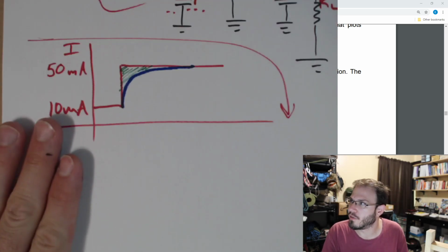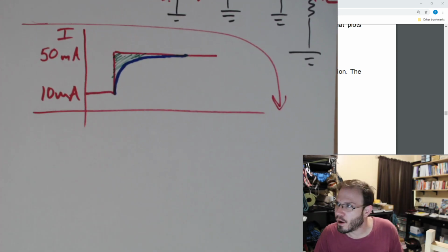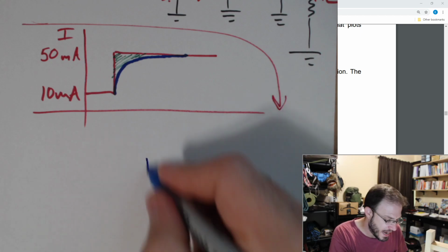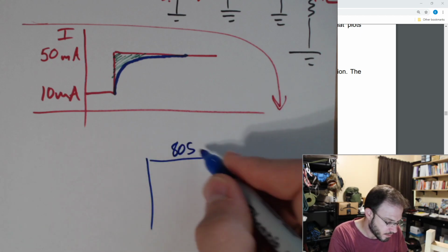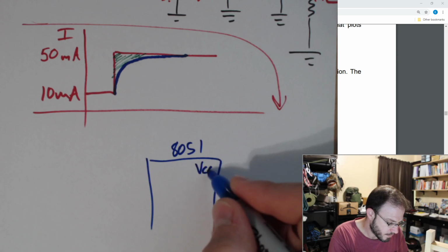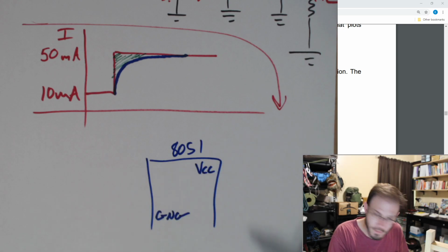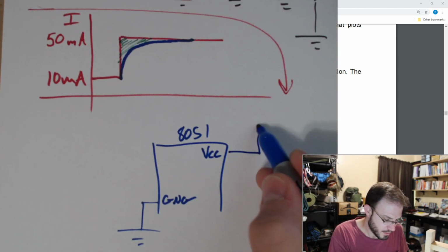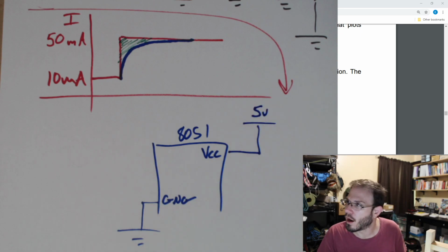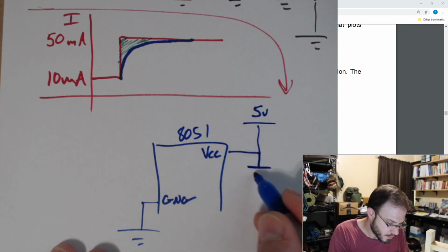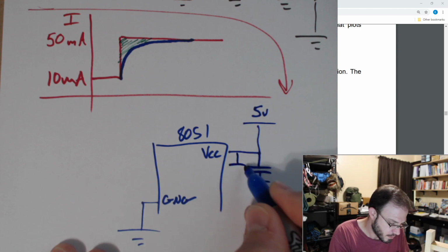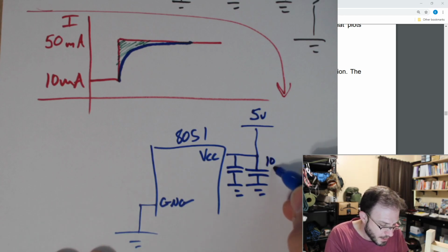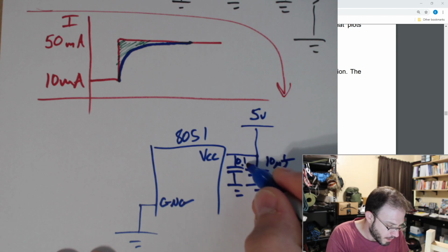And all of your digital devices, if you are in 262 and you're working with that 8051 board and you look at the schematic for that 8051 board, they're always going to attach ground and attach power, but what they're going to also do is add capacitors, and one of these might be 10 microfarad, and another one might be 0.1 microfarad.